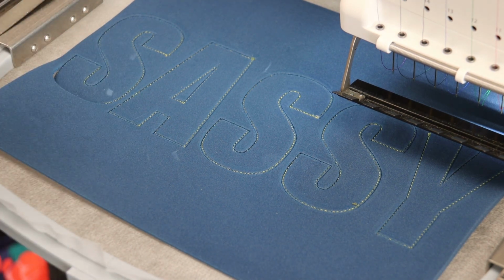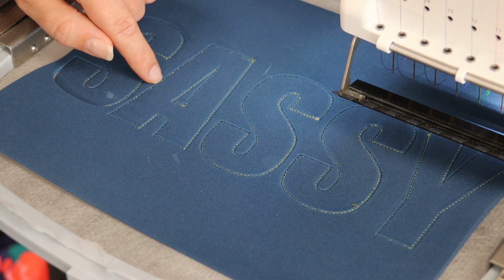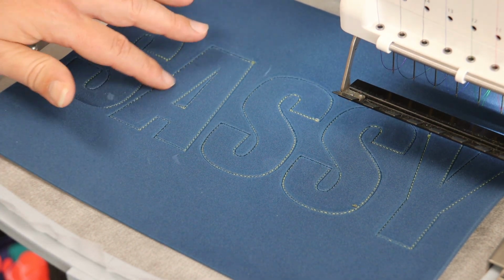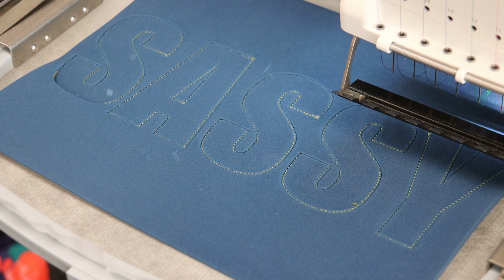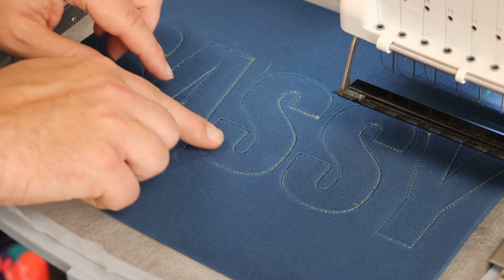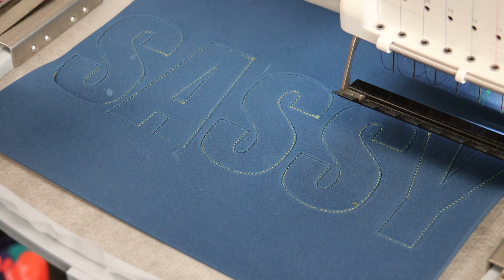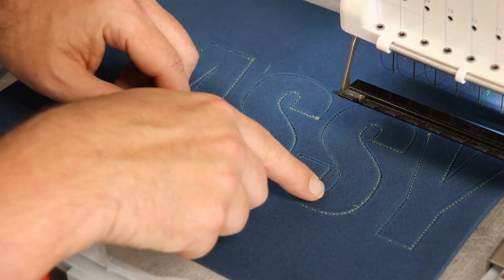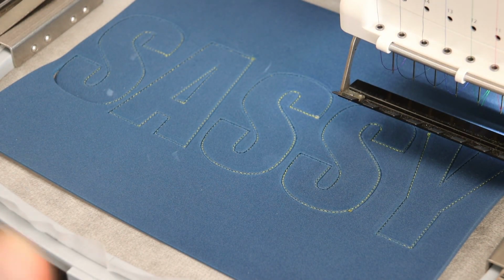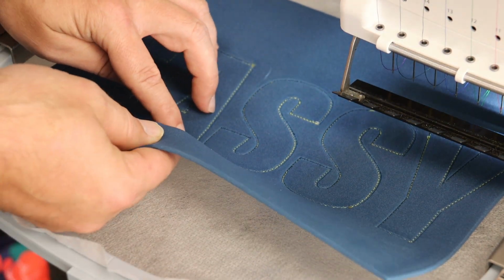If you look closely, you can see that my contour is really close to my cutting stitch. So if you're worried about the foam coming loose, what you could do is set that inner contour to 2 millimeters instead of 1. Just looking at this, I could see setting that a little bit more inset, but I also think that it's perfectly fine, especially because parts of it aren't as close. I don't think that that's going to come out of there at all, and everything will be just fine.